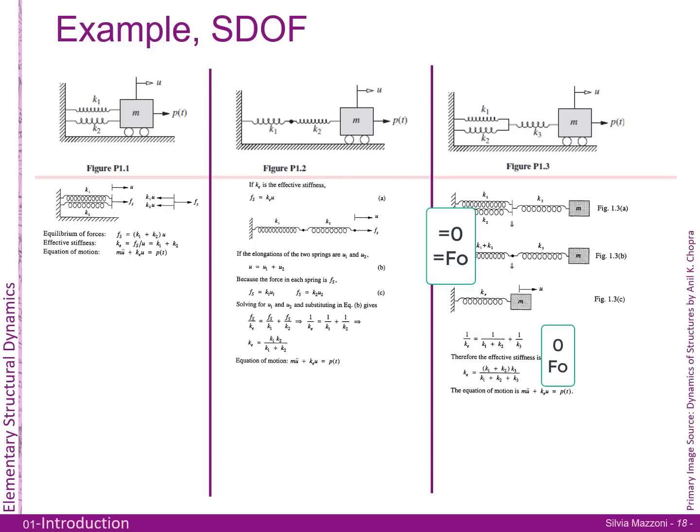And if you remember, we've done this before, in adding stiffnesses and flexibilities. I think it's just a matter of understanding what is what. In some cases, forces are additive. In some cases, deformations are additive. So let's look at each case independently. The very first case, where we've got springs in parallel, what does this tell us? If you look at this term right here, and even the free body diagram, so just pretty much the schematic here.